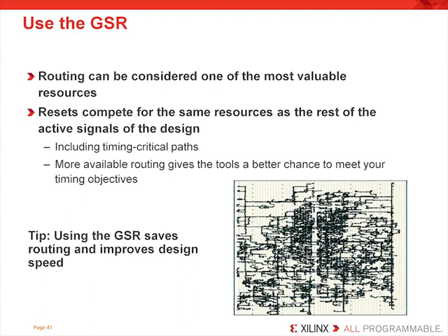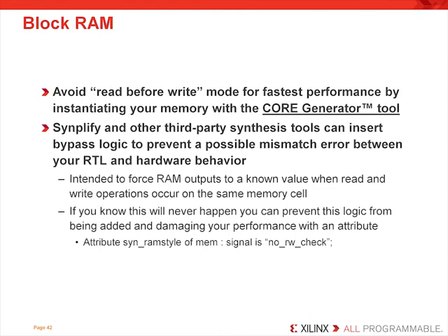You should also be aware that the tools will not automatically move resets to these dedicated clock pins, that this must be done manually. If you're going to do this, try to plan on assigning this early, since it does affect the final pinout of the device. Note that in the past, the implementation tools would infer the GSR signal for true global set resets automatically. However, the implementation tools do not do this any longer, so you'll have to assign this manually. You should also keep in mind that the block RAM's clock enable functionality has precedence over a reset. With flip-flops, the reset has precedence over the clock enable.